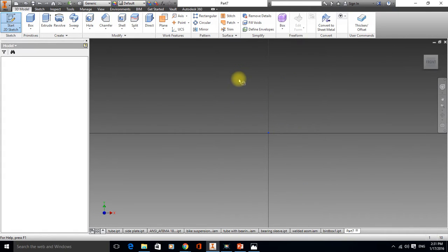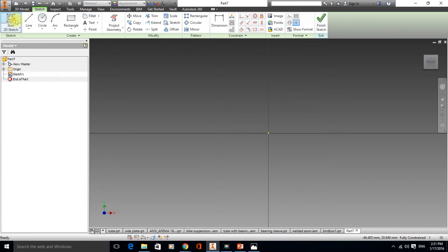So let's actually click XY, and you'll see our tabs across the top will change. Now we're going to be looking at constraints, lines, and we'll look at circles later on. And I want you to start using these. Very, very useful tools. So there's one term I want you to be aware of, and that's constraints. Another word you're going to hear is snap.